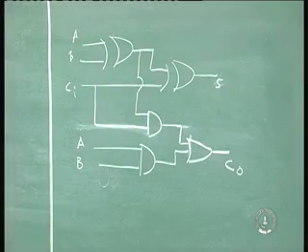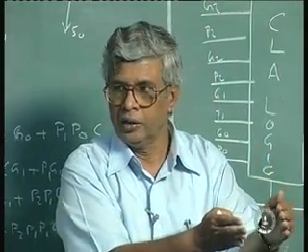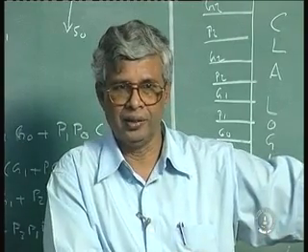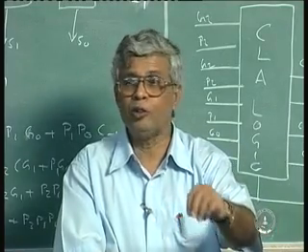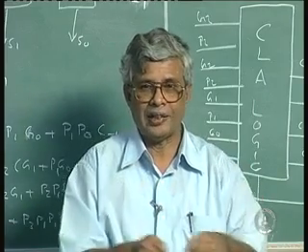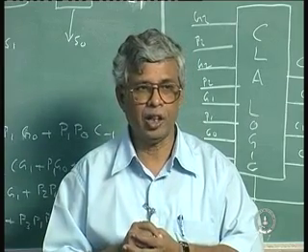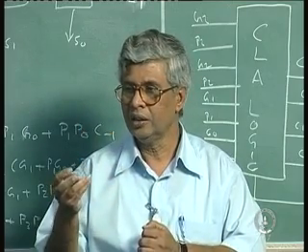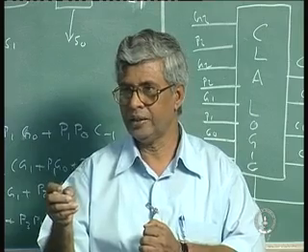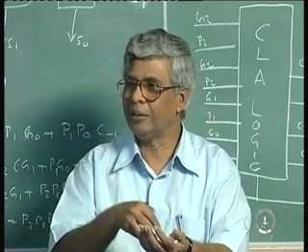One thing which is elegant here is the modularity of the circuit. That means whatever is the number of stages, all you have to do is to build an identical block. 2 bits, this repeated twice, 4 bits repeated 4 times, 8 bits repeated 8 times, 16 bits repeated 16 times. So sometimes it is easy to design circuits, especially when you want to build it in a given space. We talked about space being a premium in integrated circuit design. We talked about it in the beginning. The parameters are again to repeat the speed, the size, the cost, and the power dissipation, right. So you can pack nicely these identical circuits, called modularity, modular circuits.